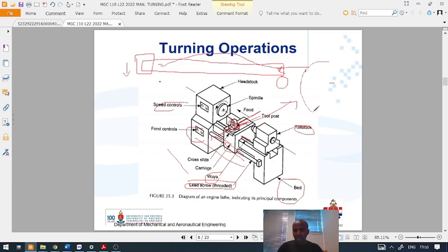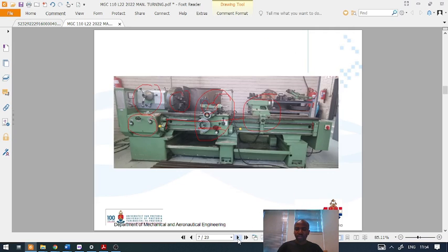If you are dealing with something that is 30 centimeters, you want to be able to work on this part in this direction, but because this is rotating, you only need to go as far as the center, or just past the center of the spindle, because you can always rotate it to bring it to this side. So you can just be here and cut the whole diameter, because your part will be rotating.